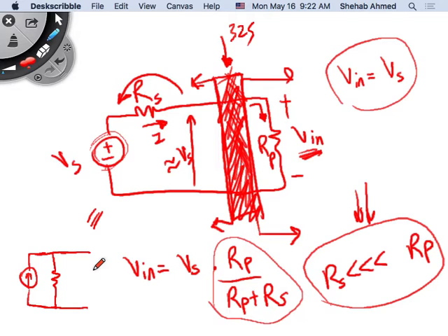If this system is drawing a little bit of current, I can represent that approximately as a resistor, like we did last time. This is the sensor current, this is the sensor resistance, and this is the RP as I put it here.